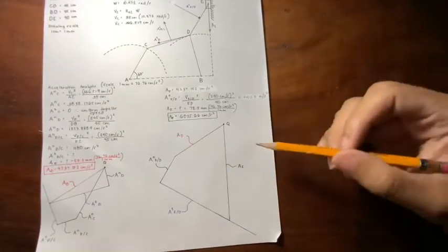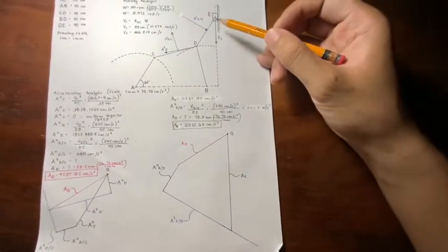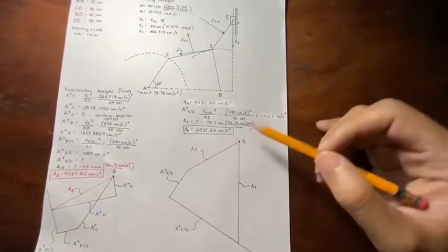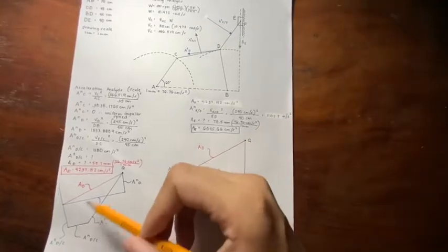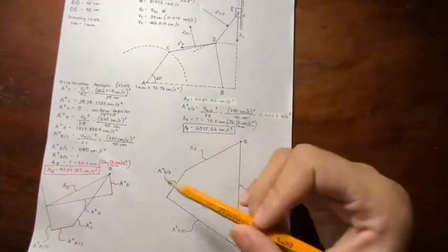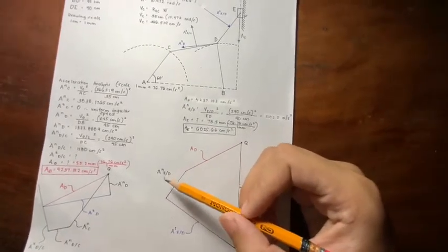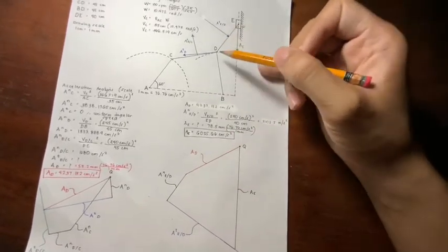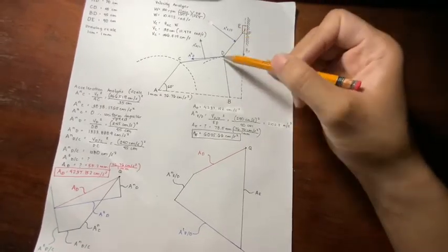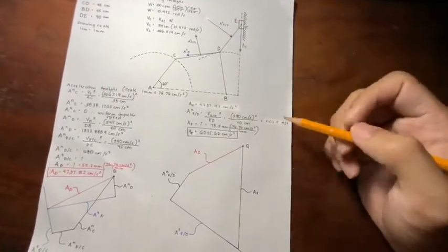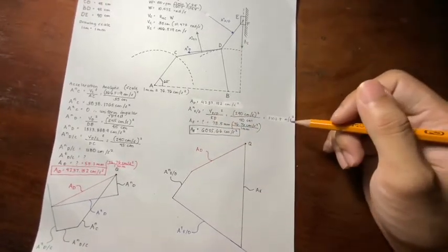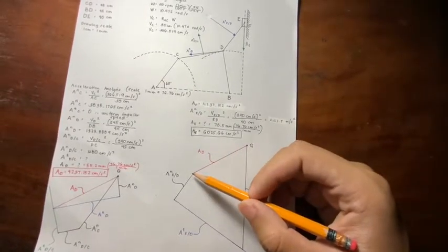Now we will solve for the acceleration at point C. We will start off by drawing the total acceleration at point D, which is given by our last analysis. We will copy that over to here, and now we will draw our normal acceleration at ED, which is the direction of it is towards or parallel to the link ED. And we also have this magnitude using the velocity we solved last activity. So now we have drawn its magnitude and direction.